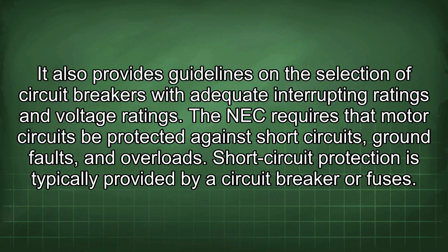The NEC requires that motor circuits be protected against short circuits, ground faults, and overloads. Short circuit protection is typically provided by a circuit breaker or fuses.